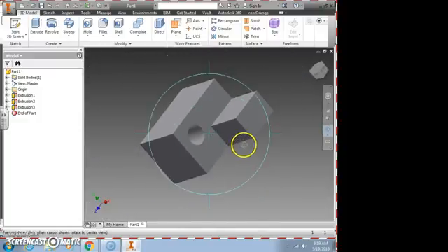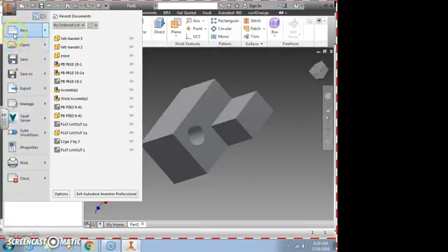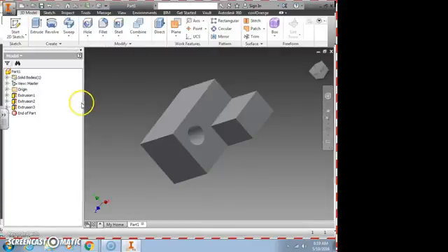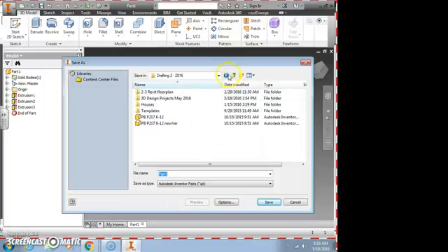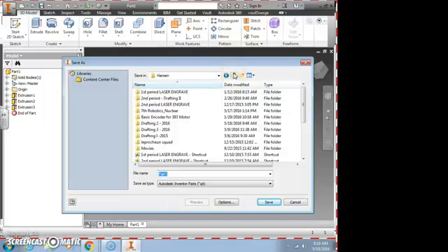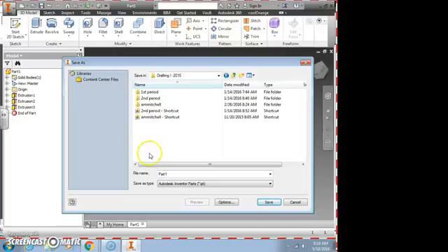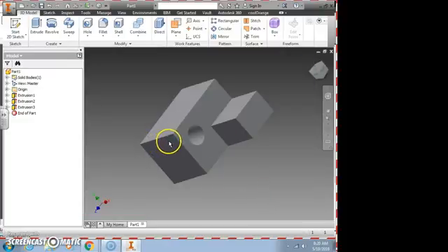All right. So let's do this. Let me show you real quick, and I know I've gone a little long with this. I'm going to save this as a part number. Let me find somewhere to save it. Where do you want to save it in our folder? I want you to create a new folder called Inventor. Okay. All right, so you can just make yourself a new folder. I'm going to put this as sample 1. So it saves as an IPT file.